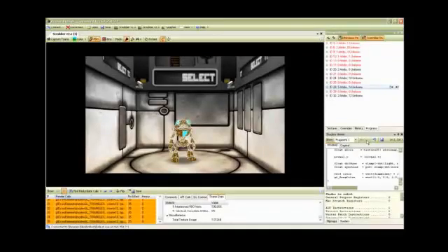So that particular change isn't practical or particularly useful, but what this illustrates is that if you want to optimize your shaders, typically what you have to do is make changes to the shader, rebuild the application, redeploy it, and see what kind of an impact that has. This allows you to greatly streamline that process, because instead of doing all that, you can simply load your shaders into here, make your changes here, and immediately see what kind of change they have, not only in performance, but in actually how it looks on the device. So this really greatly streamlines the shader development process.